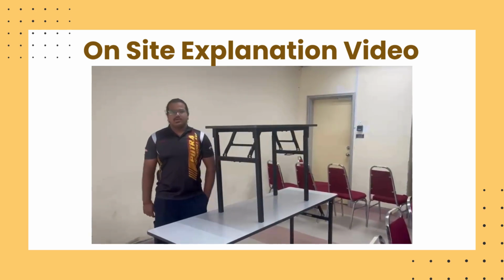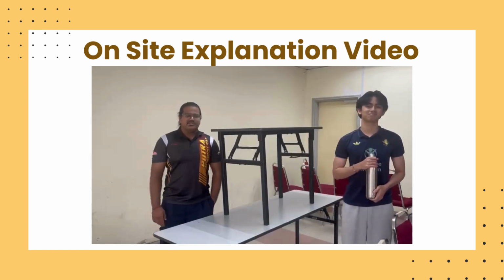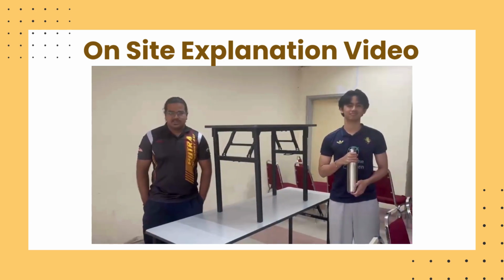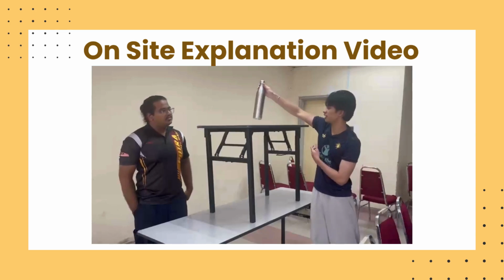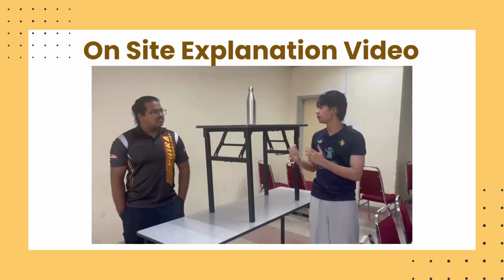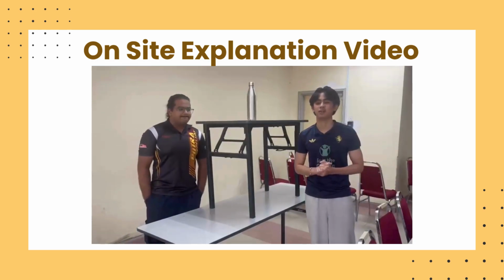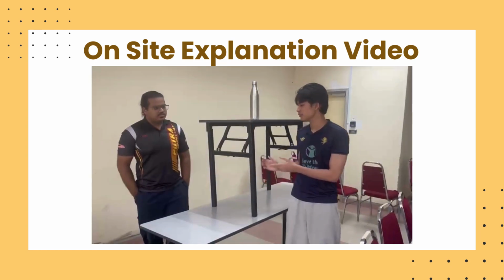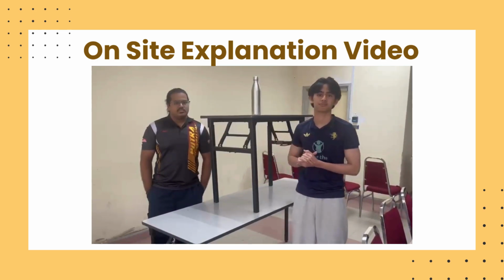Hello, today we are going to do a strength of material assignment on buckling analysis. For the structure that we have chosen, it is this folding table that we use in our everyday class. This buckling analysis starts with placing a load on this table. Over here we have our everyday item acting as our load. From this load we can tell that each of the legs, 4 legs, undergo axial compression where buckling may occur. So let's get into the dimensions of the leg. For this leg, it's a hollow 3 by 3 centimeter leg with a 60 centimeter length.